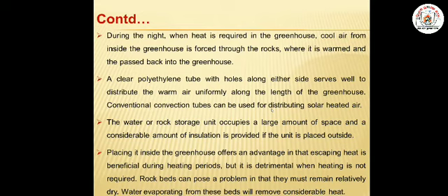Within that, in short, we have seen design criteria of greenhouse, two terms related with greenhouse. Then we have studied different cooling systems. Okay, in cooling systems, passive cooling systems and active cooling systems. In passive cooling systems, we have studied, in short, natural ventilation and roll-up side curtain arrangement. Okay, whereas in active cooling systems, forced cooling systems, we have studied the fan and pad cooling system and fog or fogger systems.